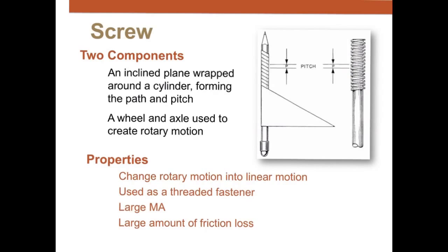Alright, so a screw is going to have a really large mechanical advantage depending on how large the screwdriver or wrench that you're using. But most of that force, of your force effort, is going to be lost to friction. But if you think about it, you want all of that friction there, because when you're putting a screw into something, you're trying to hold it in place.